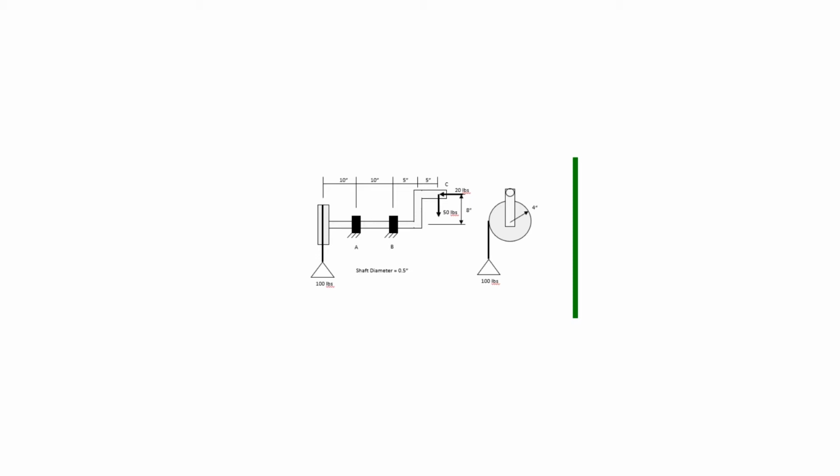We'll build a model to compute stresses and deflections, as well as reaction loads. We will also use the model to compute and plot shear moment diagrams. The problem we are going to solve consists of a hand crank that is used to lift a 100-pound load as shown. A person is to turn the hand crank and wrap the cable around the end disc, which then lifts the 100-pound load.